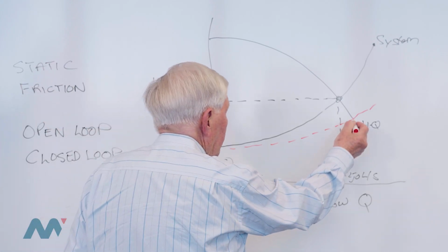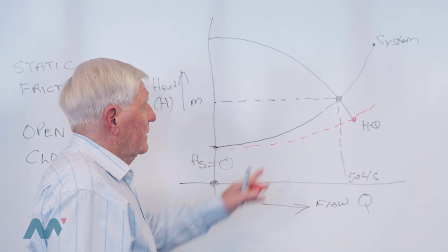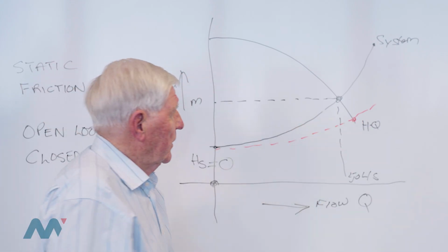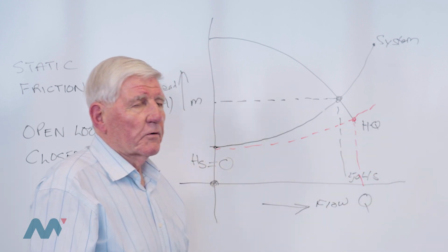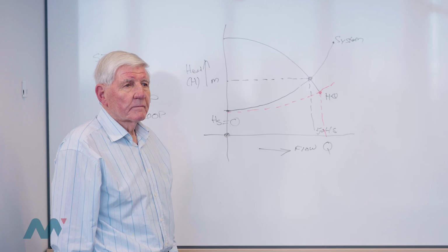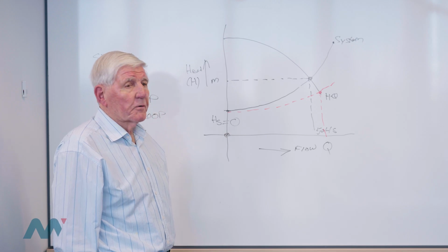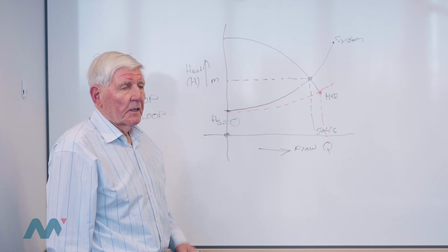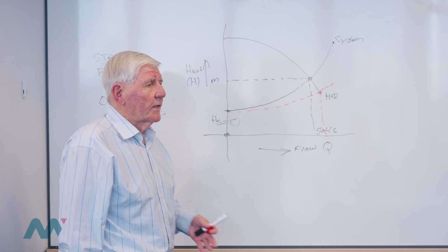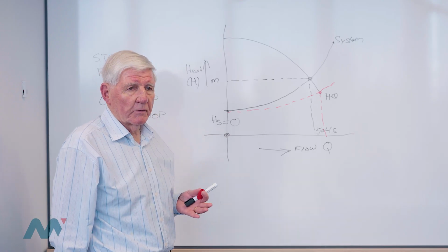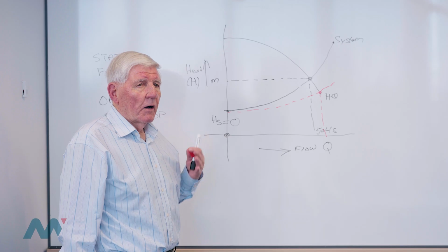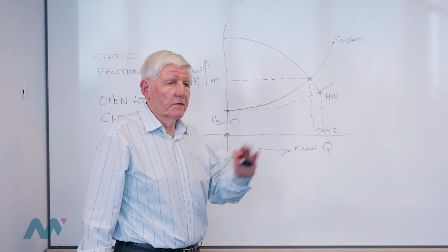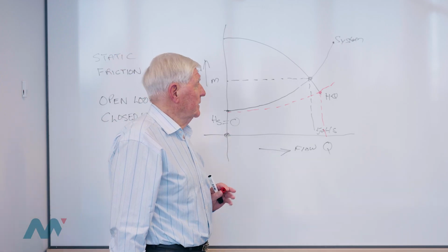The pump will operate here. And that could be right at the end of the curve. And in this situation, the pump will be operating very unhappily. Okay? It's not a preferred operating zone for the pump. You will get vibration, you will get noise, you will get premature component failure. That is the inevitable outcome of operating a pump too far to the right of best efficiency.